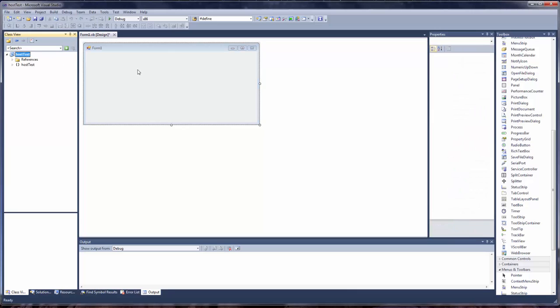Before we go any further, one of the first things you're going to want to do is make sure that the runtime library, that's the DLL for the AIB2 runtime, the manifest file, and the original exported runtime file are in the right directory.